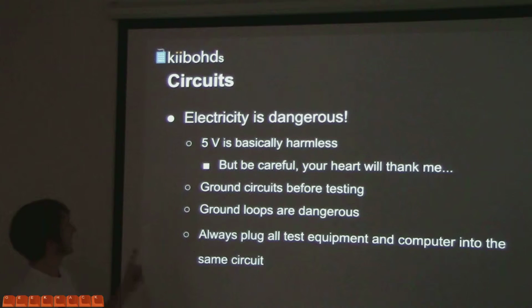Like I mentioned earlier, electricity is dangerous. 5 volts is harmless, basically. So during this demo, I can touch it and do things. But things you don't want to do: hold plus in one hand and minus in the other. You're making a circuit. You don't want it to go through your heart. It doesn't take that much to actually stop your heart. Current is very dangerous. High voltage is very dangerous.